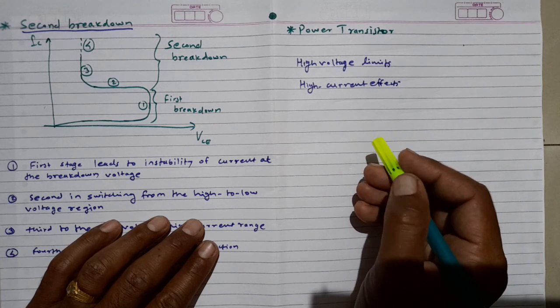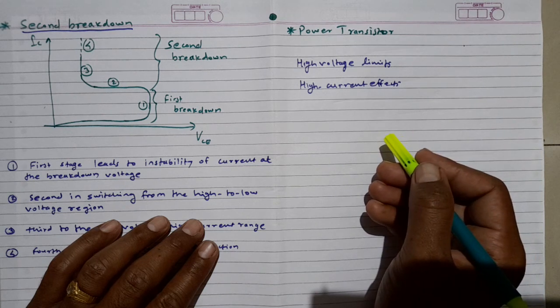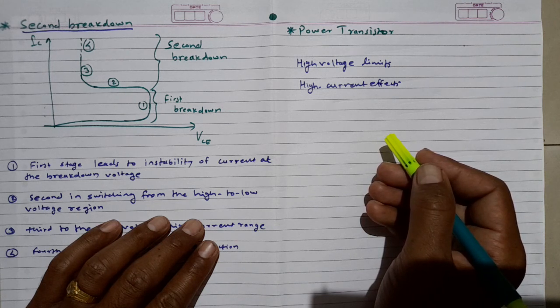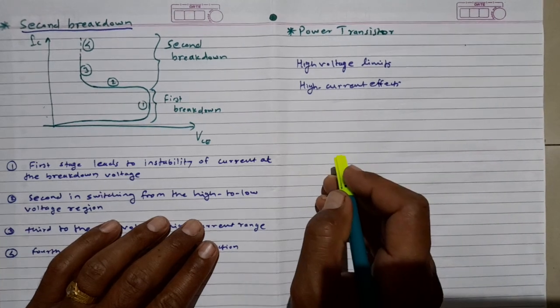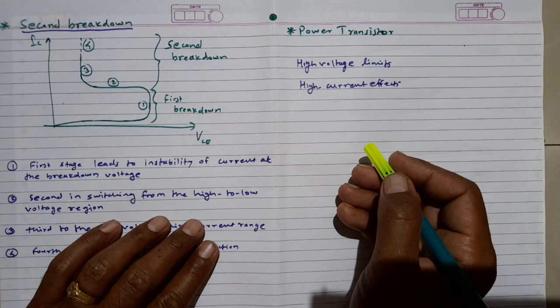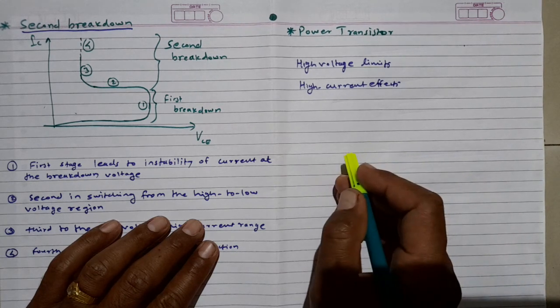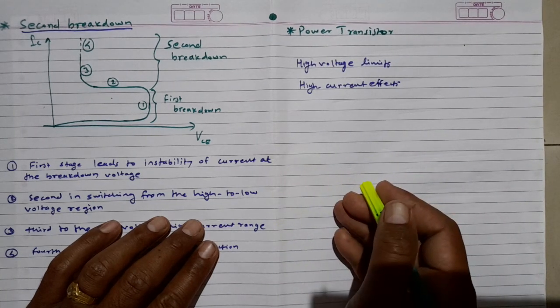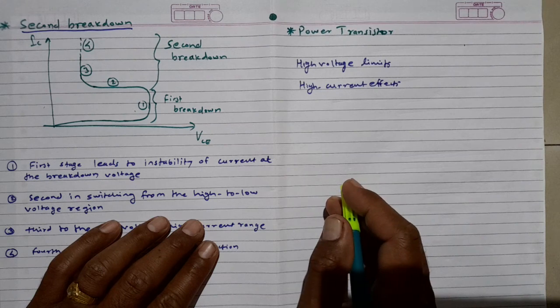Now when we are trying to design power transistors, a trade-off between the power and the speed has to be compensated, because the power and the frequency product is mainly limited by its material properties, or some material parameters related to it.